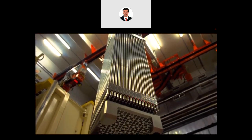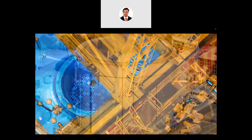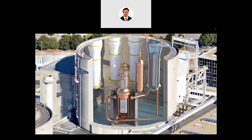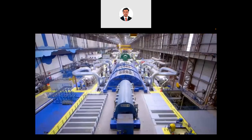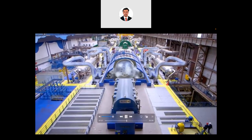The fuel used by a nuclear power plant takes the form of small uranium pellets that are stacked in long metal tubes known as fuel rods. These tubes are placed in a steel tank filled with water, the reactor's core. The fission of the uranium atoms heats the tubes, which in turn heat the water to a temperature of 320 degrees. Pressurized to keep it in a liquid state, this water is then channeled to the steam generators. When secondary system water enters into contact with the primary system's pipes, which contain very hot water, it heats up in turn and becomes steam.